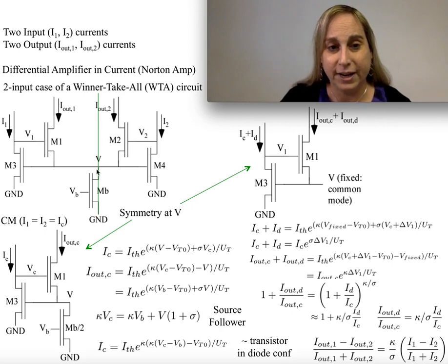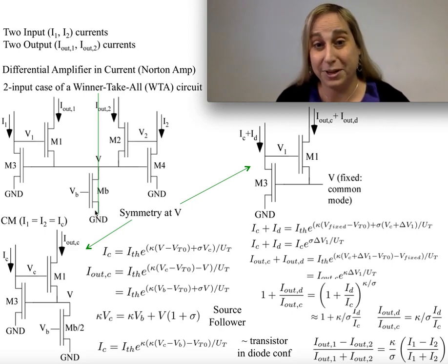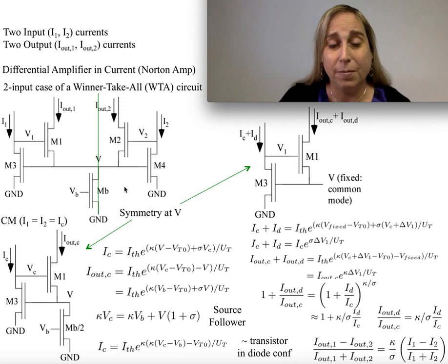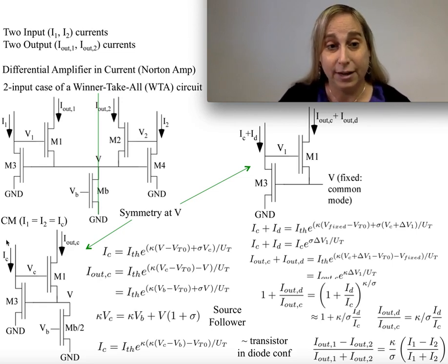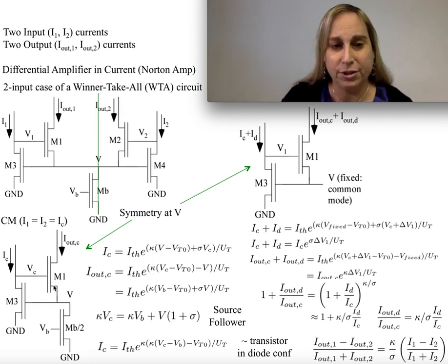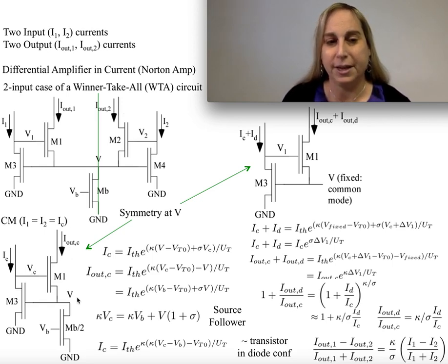So if I just divide this in half, which is why I said MB will be twice everybody else, I end up with a core circuit underneath, where I have the common current, which is I1 and I2, so they're identical. I'd expect V1 and V2 to be identical voltages, V is the same, and these 2 currents are the same. Not surprising how this works. That's a common output current, common voltage, and the middle node is still the same.